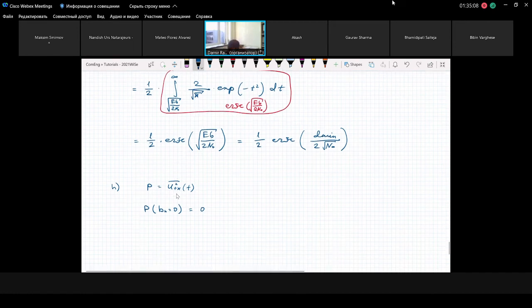And if we transmit bit equals to 1, then we have this rectangular pulse, which is scaled by 2 EB. When we calculate square value of it, we get that the power will be 2 EB. This is the power when we transmit the bit equals to 1. And what will be the average? You just take the probability that you observe bit equals to 0 times its power, plus the probability that you observe bit equals to 1 times the corresponding value of power. This is how we get this average power.